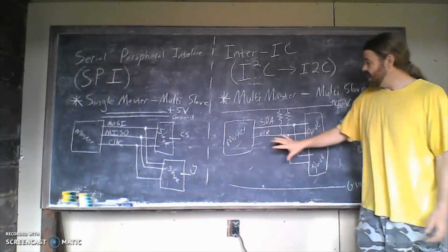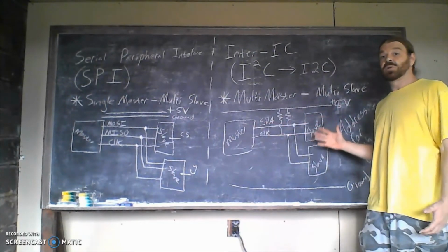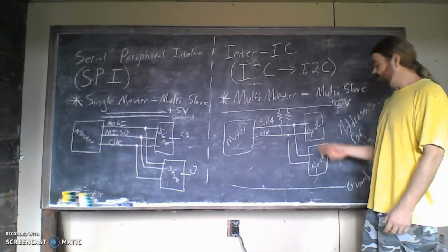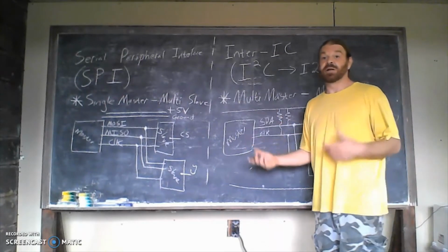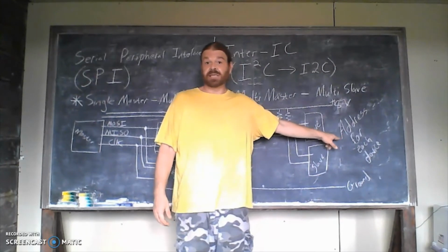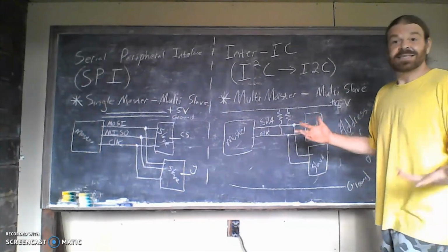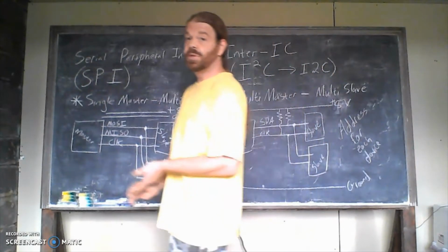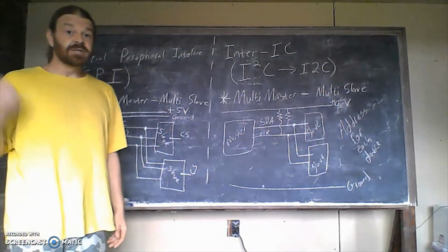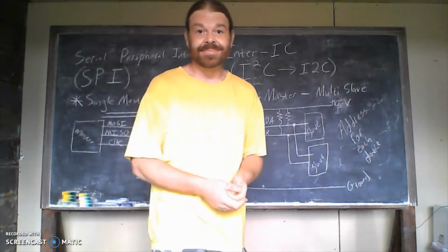With I2C, we keep these lines high at all times, so as soon as something wants to communicate, it sends out a 0. So we keep a 1 on the line, and as soon as something wants to communicate, it sends a 0 down the line, and whenever a 0 comes down that line, everything listens, and if it hears its own address, then it's the one that responds. So that's a start, an introduction into these intra-device communication protocols, SPI and I2C. So let's go back over to the circuit and kind of take a look at these in action.